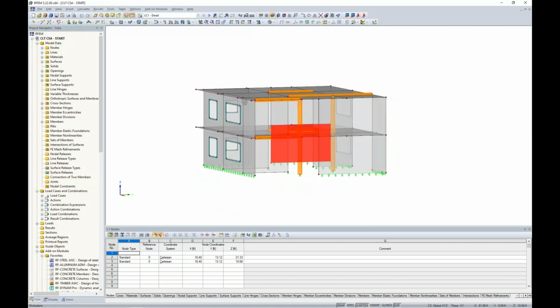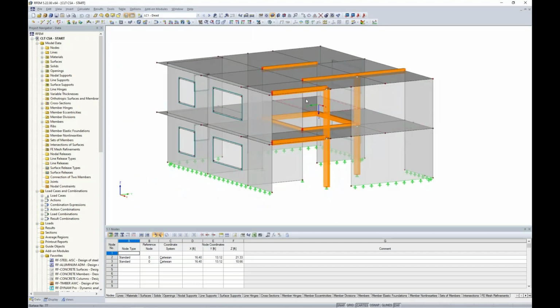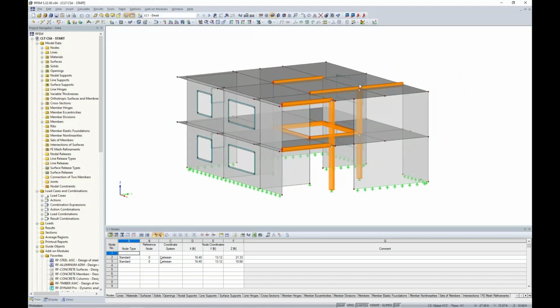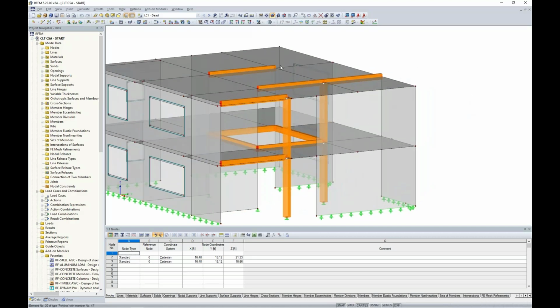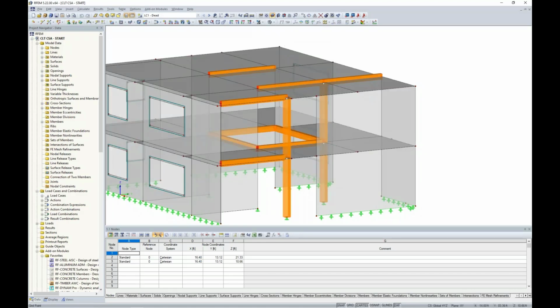You'll also notice that I have some beam members within the program as well as columns. So these are just typical glulam members. For example, we have these beams here that will be holding up certain portions of our CLT ceiling up at the roof. And what you'll find when we turn this into wireframe view is that 1D members are represented by 1D line elements. And so inevitably when we turn this into the rendered version here, you can see that the center line of the beams lines up with the center lines of the CLT panels, when in fact we'd actually like to drop these glulam beams below the CLT panels.